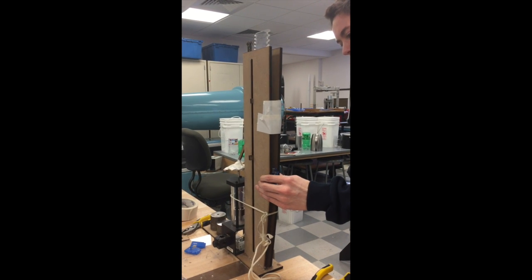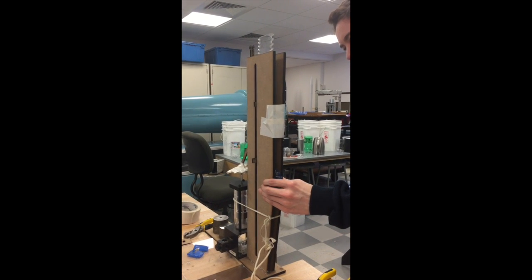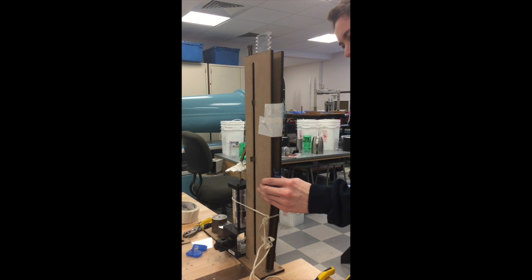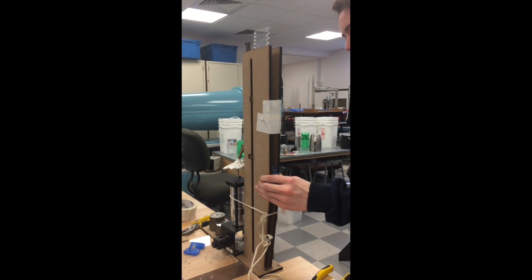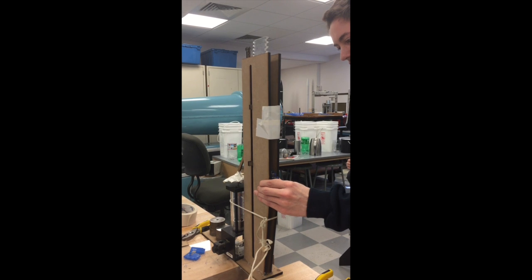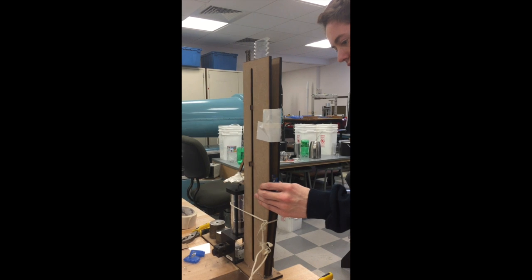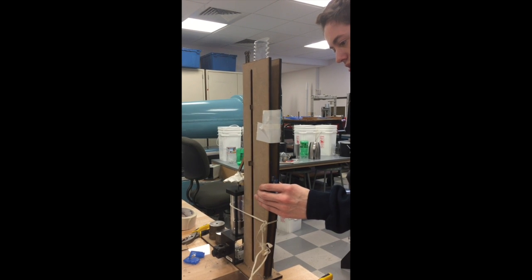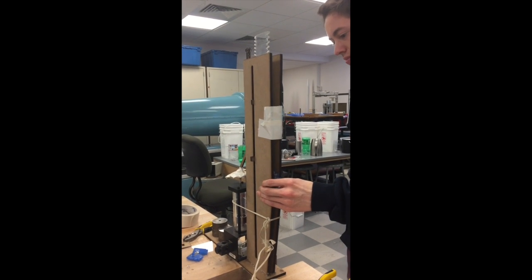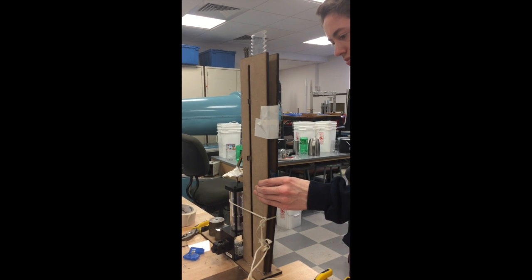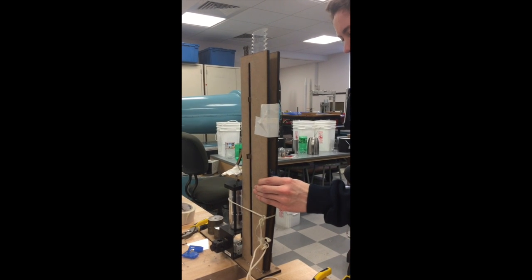Some things that we could have done to improve our performance was to use acrylic instead of MDF for the rack and the walls of our mechanism, as this would have greatly reduced friction that exists in the system. Additionally, calculating the distance between the teeth would have greatly improved our ability to prevent our rack from falling back down, which would have increased our overall energy stored. Additionally, finding a better way to actually implement our one-way bearing on the axle would have created a more independently working system, which was the ultimate goal of the assignment.